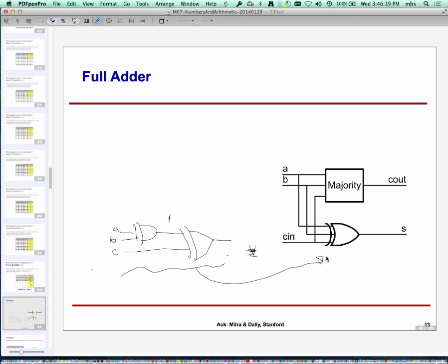And in fact, you can construct more XOR gates like this. One of the homework problems that I handed out touches upon this topic. So just remember, an XOR gate basically lets me check for an odd number of 1s. Okay? And if I gang them up, it is basically creating a multi-input XOR gate whose property again is that it checks for an odd number of 1s.